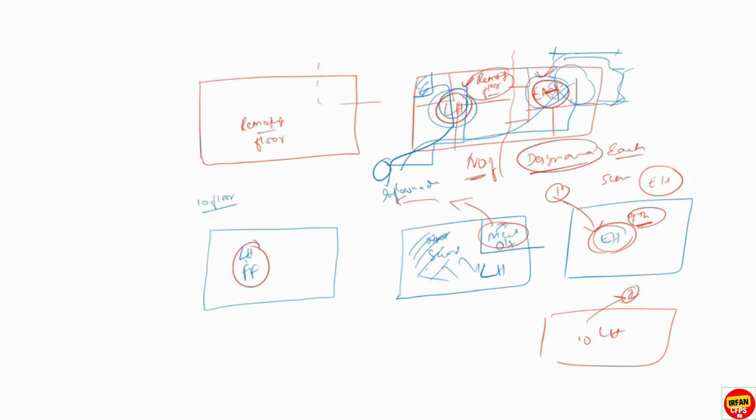So just remember these things. If you have various hazard occupancies, you have to consider different scenarios for performing the calculations to get the proper flow requirement at the inflow node. Only then can we select the pump requirement. But as I already told you, if you have hydrants and fire hose cabinets in your project, and sprinklers also, then you need to select the highest flow and highest pressure to select the fire pumps.